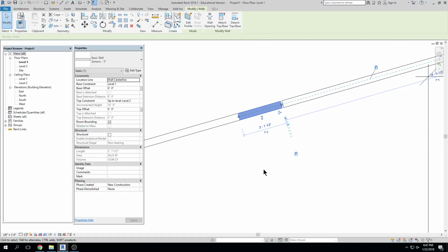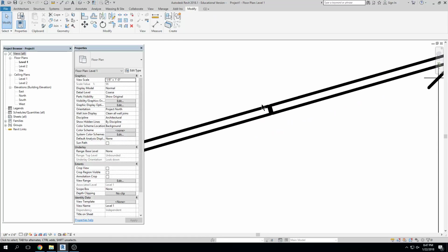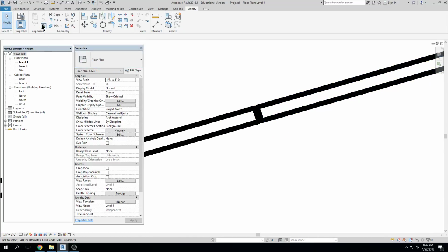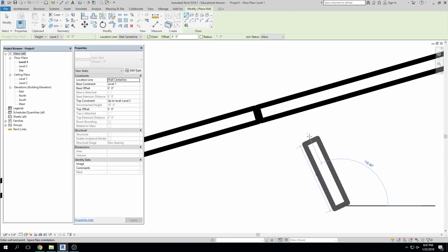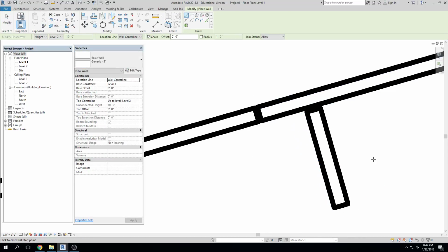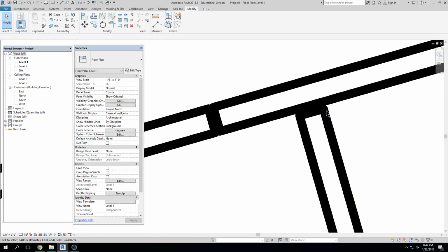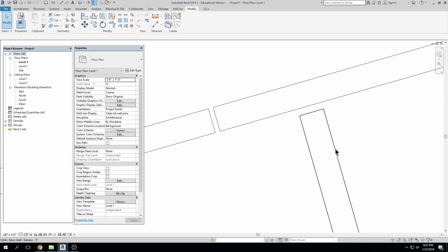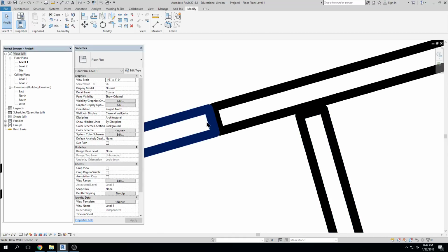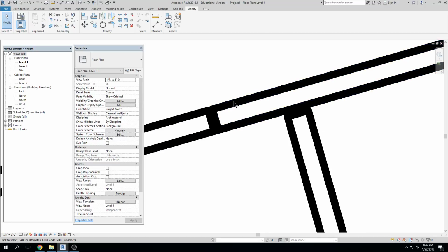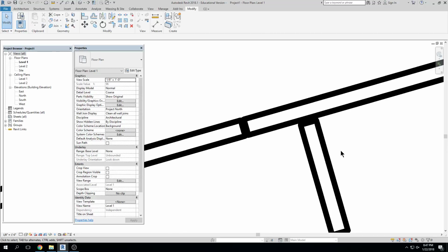Wouldn't it be better to draw with thin lines and then? Well, the problem with thin lines is I feel like it sort of blurs the edge. Does that make sense? So when I'm drawing, let's say I'm drawing a wall, and I want it to join this other wall. And you're like, oh, there it is. Well, it's touching. Well, not really, right? And if I go to thin lines, do you see there's actually quite a gap right there where it sort of obscures that? This looks okay right now, but if I had a bunch of striations showing drywall and brick and all those things, all of those lines get very heavy and hard to read when you're trying to align to a certain place on a wall. But it's easy enough. TL, thin lines, and it goes away. TL, thin lines, and it comes back.